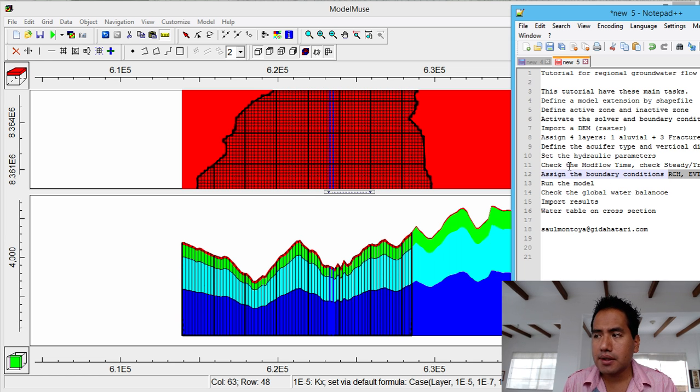In this case, I will apply a uniform recharge and uniform evapotranspiration to this model, because we know that in fact it changed, and I will explain how those changes. But in order to do the linear regression could be a little bit trickier, and I want to make sure that you finish this tutorial, and then that you can redo this tutorial on your own. So I'm not going to use the distribution. First, I'm going to import to assign the drain package.